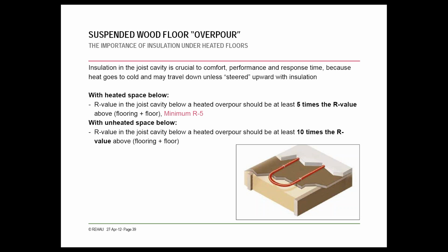So in terms of what's the minimum required, you should double check with the code requirement in your local jurisdiction. Most of the time it's not required underneath the slab if you're using edge insulation already, so there's no minimum, but depending on the application, there may be a minimum required. If you have a specific application that you have questions about, again, feel free to contact me, or I'll give you my contact info again at the end, and we can certainly help make sure that the specific code in your area is being followed.